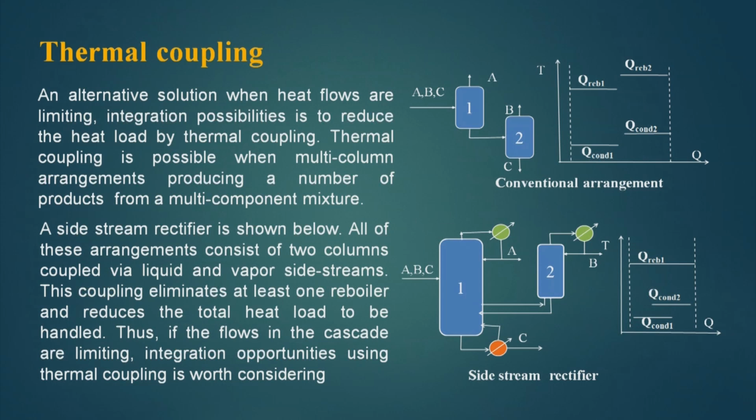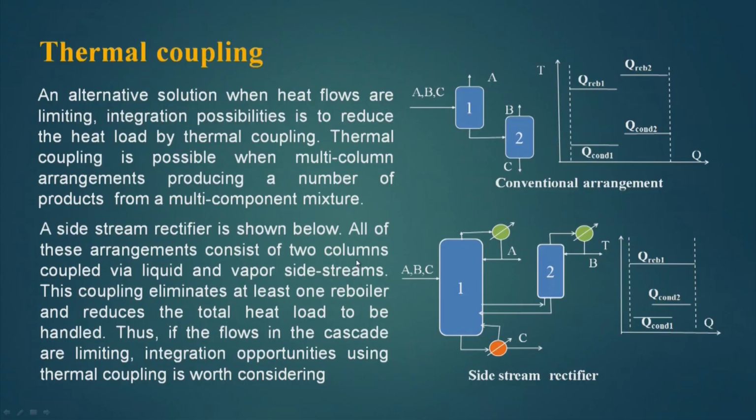We have seen that it is not only a matter of whether the distillation column is placed above, below or across the pinch. The heat flows also have to be checked. If the heat flows become negative, then integration is not possible. So, in those cases thermal coupling is worth considering.